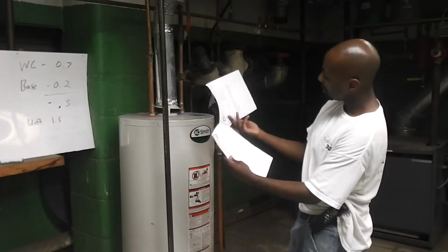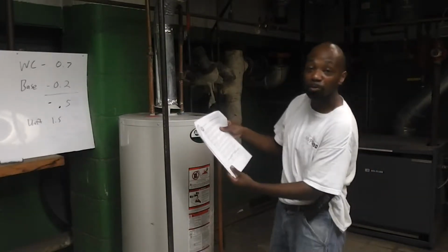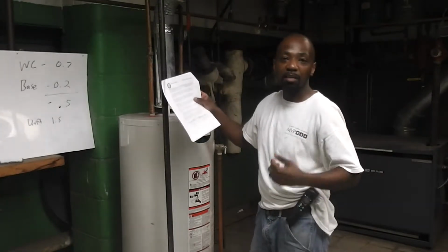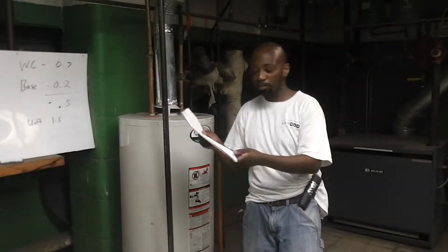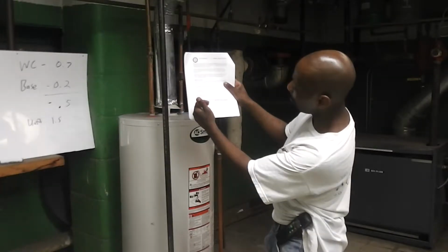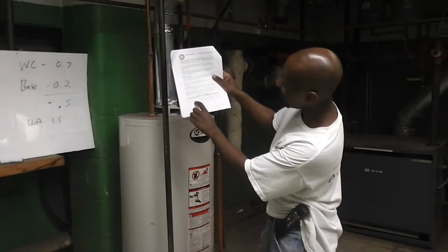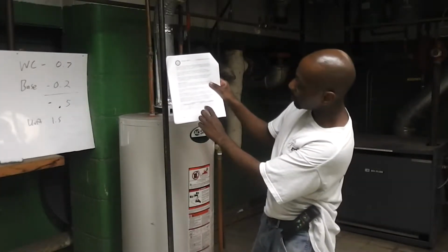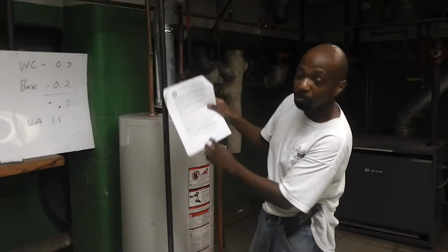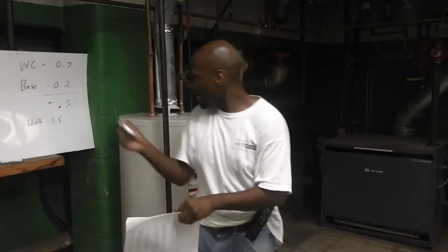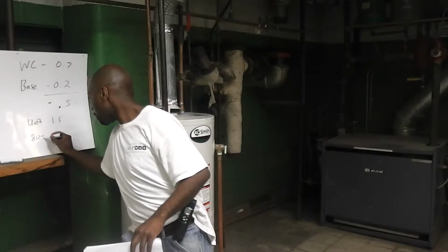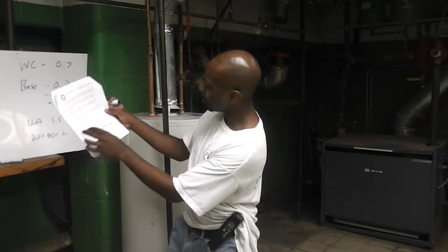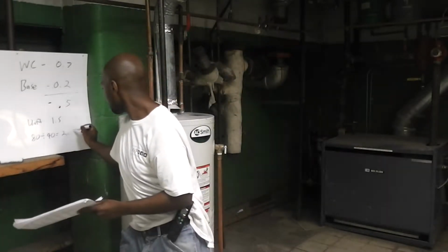On the standards, we're going to look for our acceptable draft ranges. That's on page 10. It looks like it depends on the temperature outside. Last time I checked, temperature outside is 80 degrees. According to the chart, it's more than 10, less than 90. We're in this range. In this range, there's an actual formula you have to do: the outside temperature divided by 40 minus 2.75. The outside temperature was 80 degrees. I want to divide that by 40. That'll give me 2.